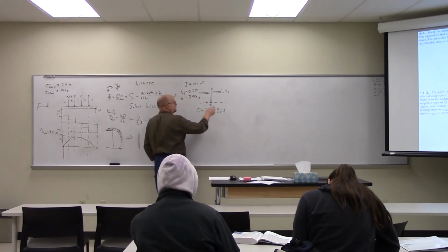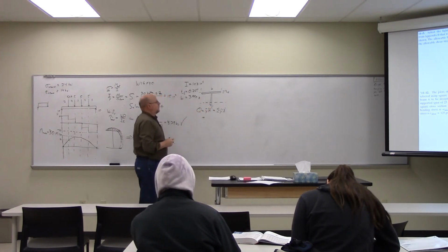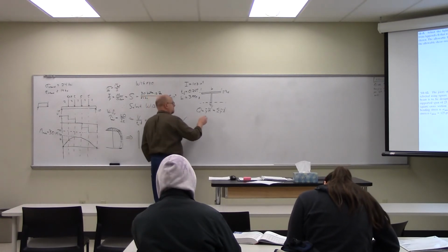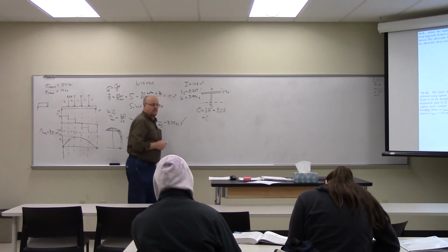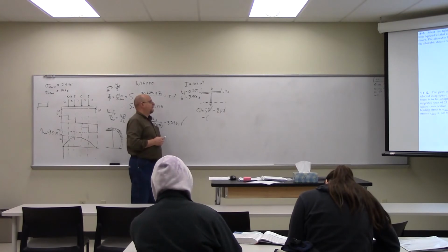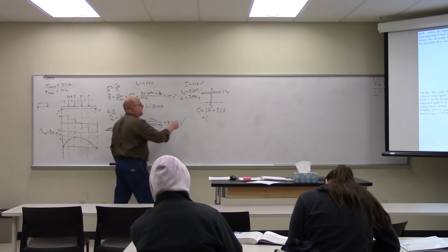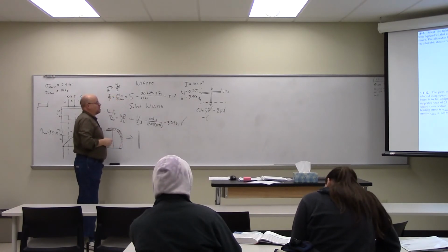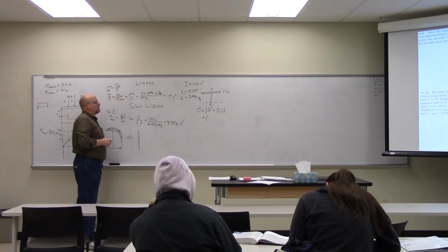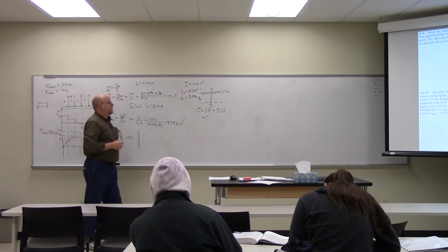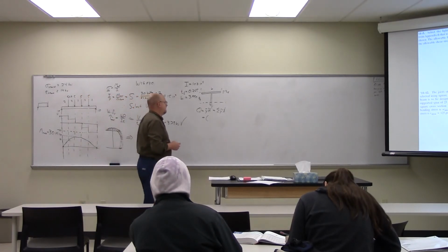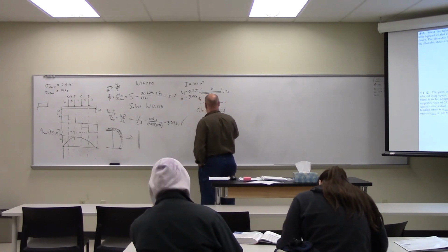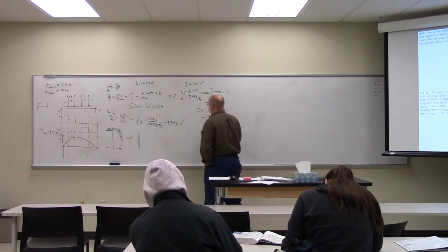Okay, so what is Y tilde prime A prime for the top piece? What's Y tilde for the top piece? This is actually D over 2, TF over 2, so 0.1325. No. Plus the height. So it's actually going to be D over 2 minus TF over 2.